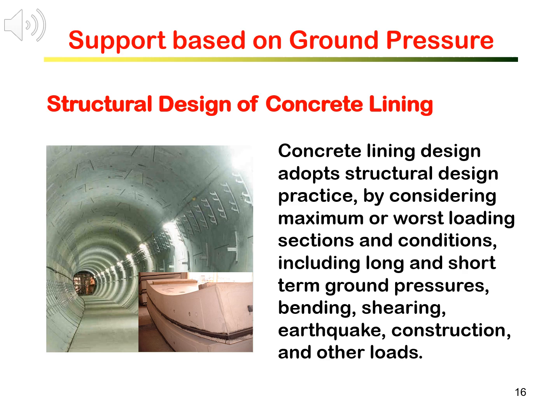Supporting structures, for example, steel ribs and concrete linings, are designed as load-carrying structures. Concrete linings are the most commonly used tunnel support in weak and poor rock masses and soils. Concrete lining design adopts structural design practice by considering maximum or worst loading conditions in terms of compression, tension, shear, and bending for short-term and long-term.